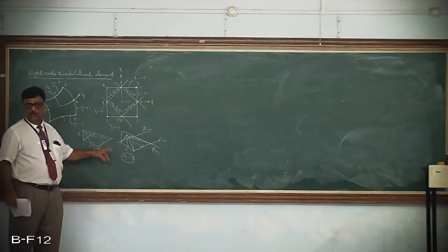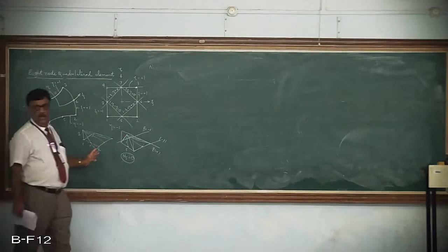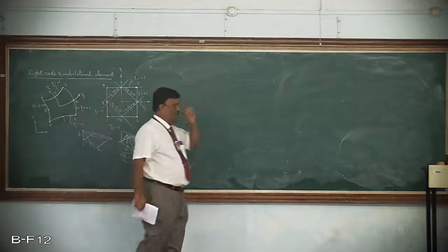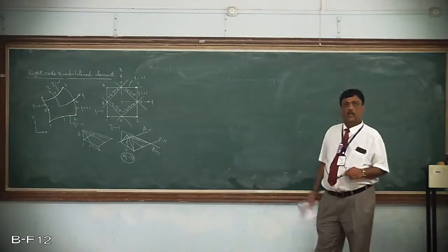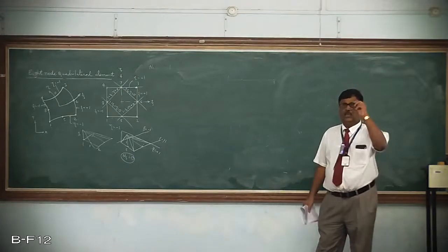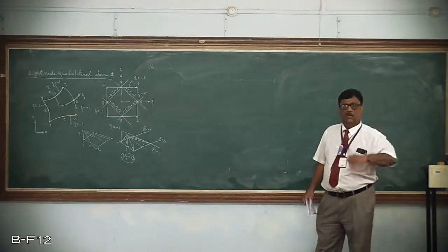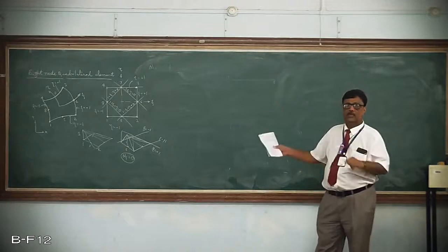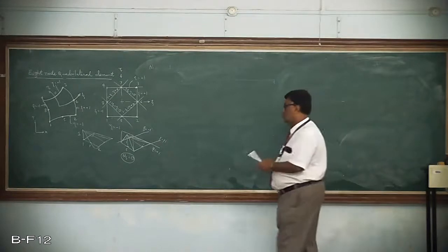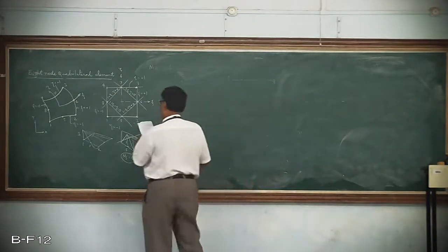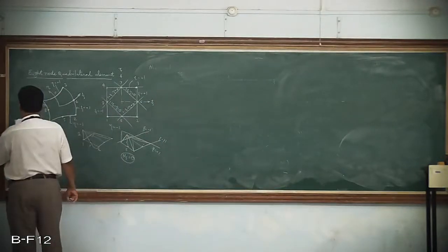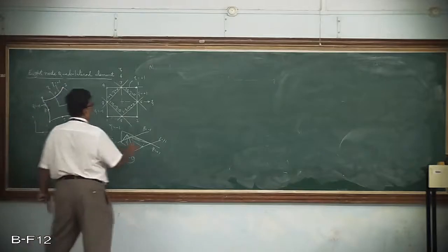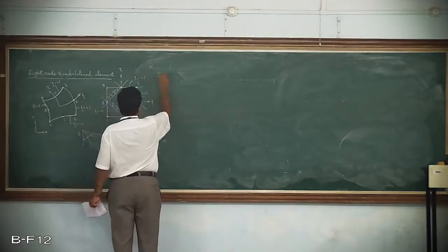So due to this different type of property, at a time I cannot solve all the shape functions here. Therefore, first I will define the first 4 functions, n1, n2, n3, n4, and then I will define the remaining, that is n5, n6, n7, n8. So let us quickly look at that. This is also called an element belonging to the serendipity family.